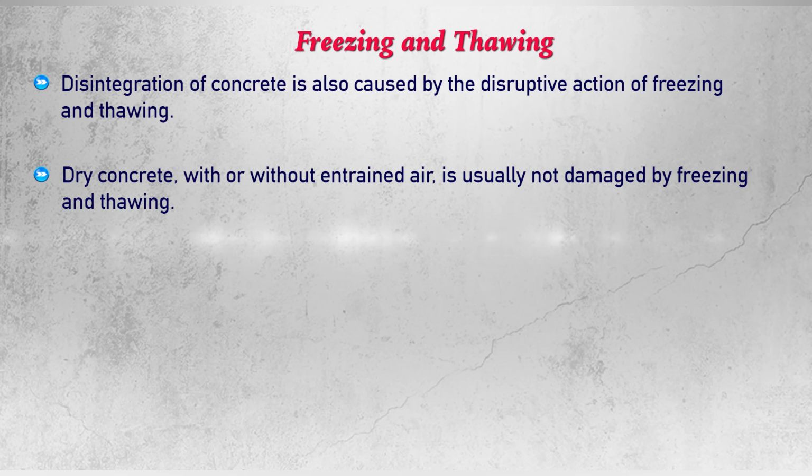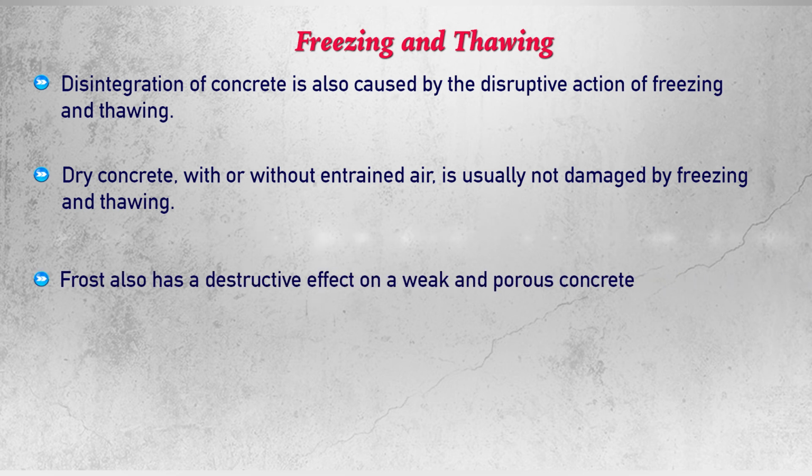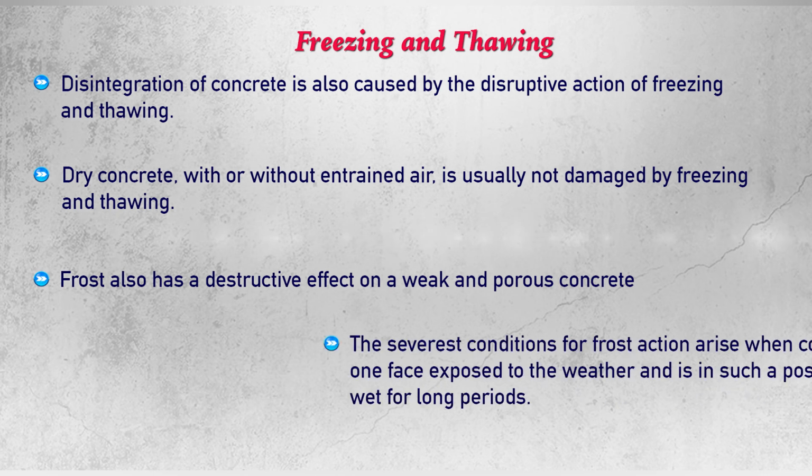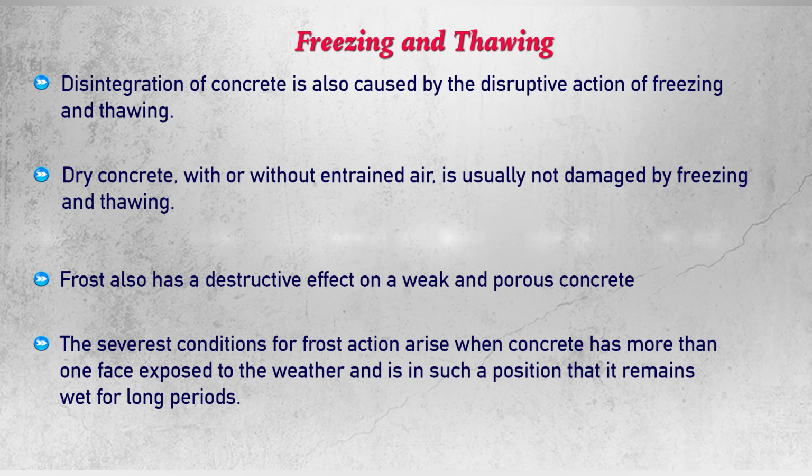So that way freezing and thawing causes stresses in the concrete. Dry concrete with or without entrained air is usually not damaged by freezing and thawing. Frost also has a destructive effect on a weak and porous concrete. The severest conditions for frost action arise when concrete has more than one phase exposed to the weather and is in such a position that it remains wet for long periods. Alternate wetting and drying has also an adverse effect on the concrete.